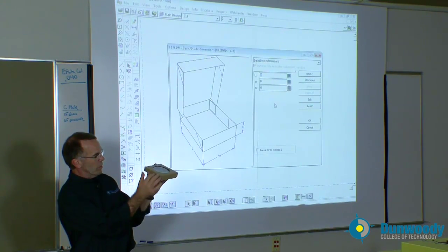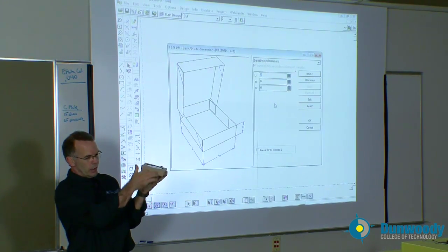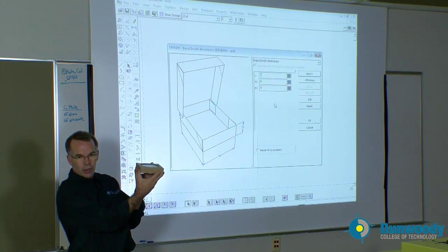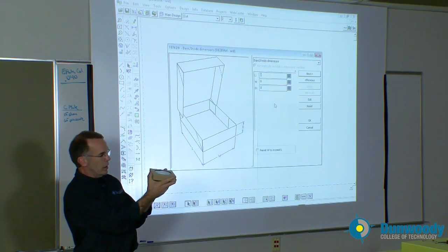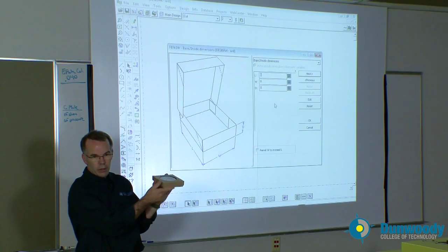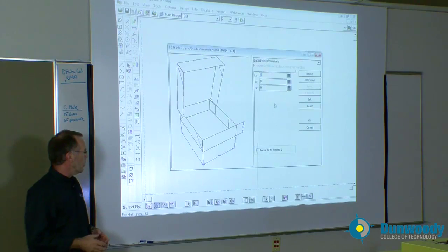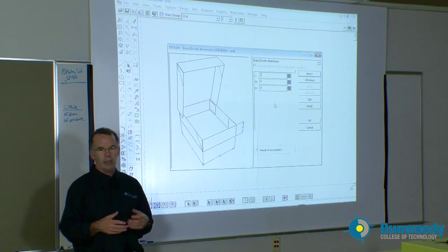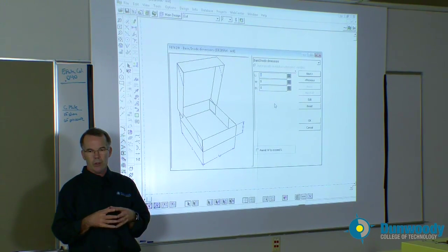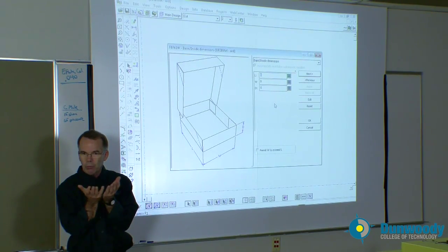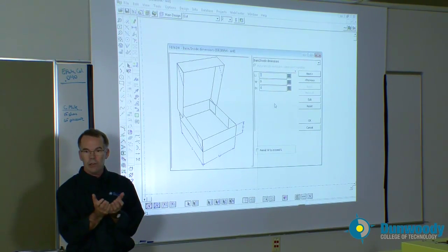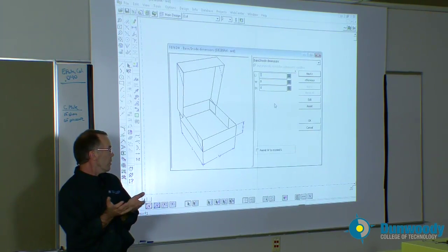So we've got length, we've got width, and then the depth is the height of the carton when the carton is closed. And that's how we define folding carton dimensions, which is very important because shelf length in the Western world is divided into 4-foot lengths. And we always want to design knowing that we want to pack as many specific cartons into that 4-foot length as possible.